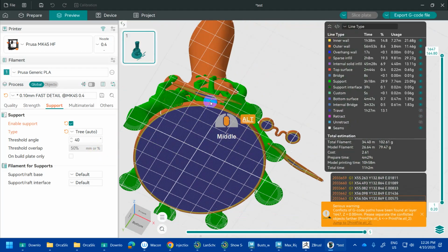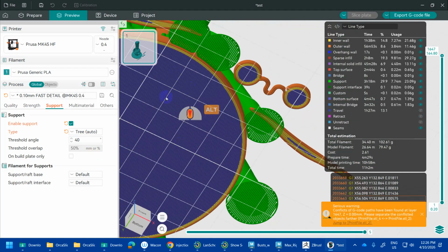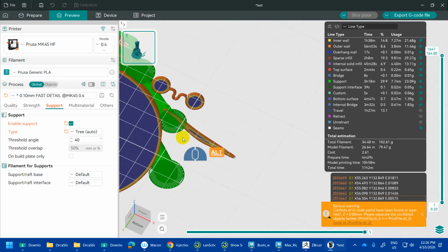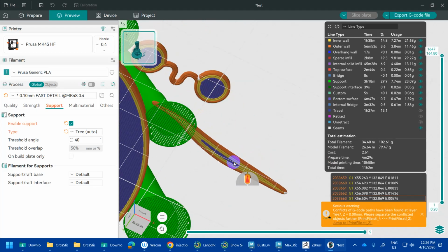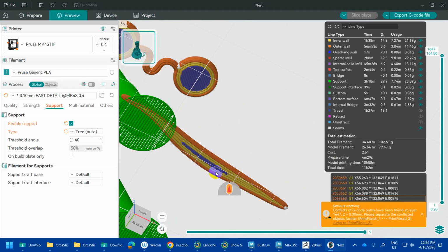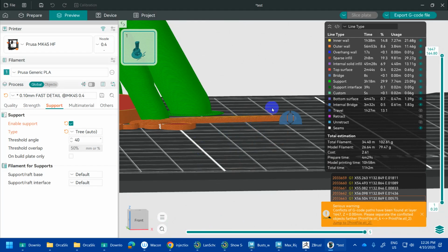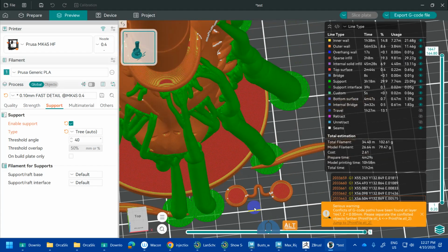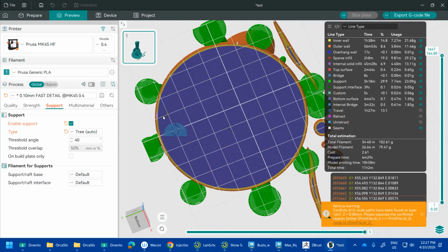Yeah, one last thing you should double check is the bottom here. So sometimes, like I said, if things are not perfectly flat, which is one of the reasons why I created just a simple cylinder and used the trim curve or clip curve to create a nice flat shape, sometimes when there's a curvature and it's off the build plate, you'll have a void with something curling up, kind of like the sphere, right? So it can create some other problems and create some scarring or some print errors. So that's why I try to create nice, flat, solid areas so that you get a good adhesion.